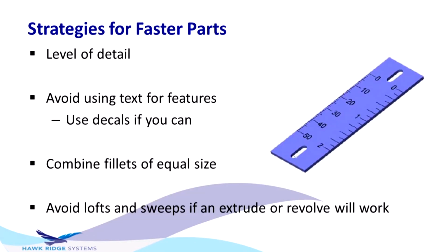So where we're talking about level of detail, use decals if you can, combine fillets of equal sizes. And the last one is hard to apply, but it's essentially if you can use extrudes and revolves versus lofts and sweeps, we find that those rebuild times are much faster.